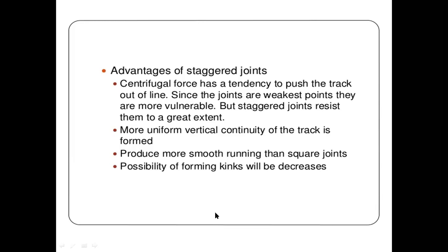If we consider these margin lines as a rail, and this line is also a rail track, and a joint is seen here similar to the opposite side, these joints are known as square joints. For a staggered joint, if a joint is here, the other track has the middle of its rail here, so there must be a joint at some other point like here.